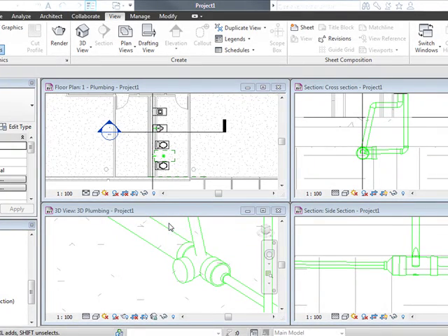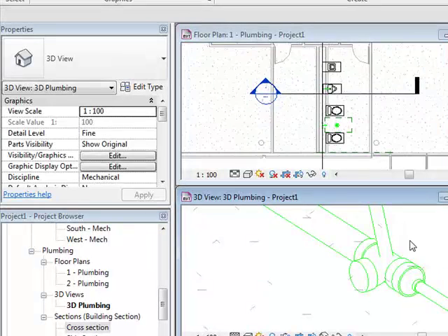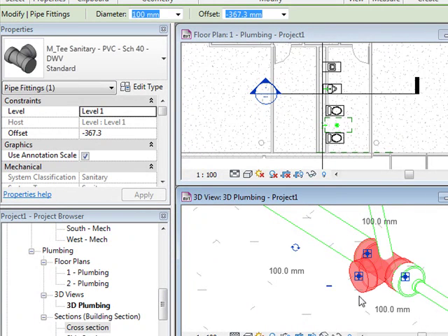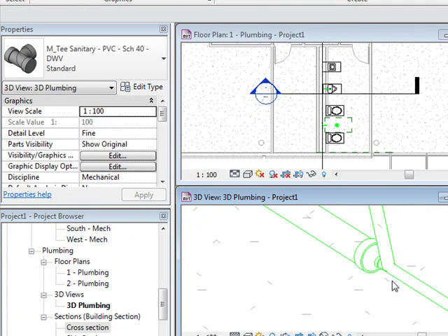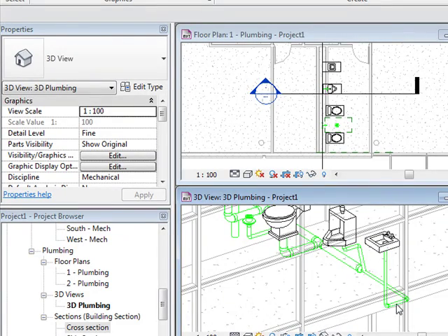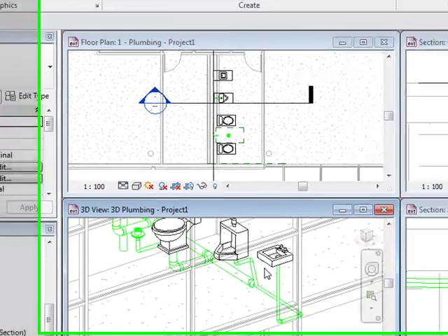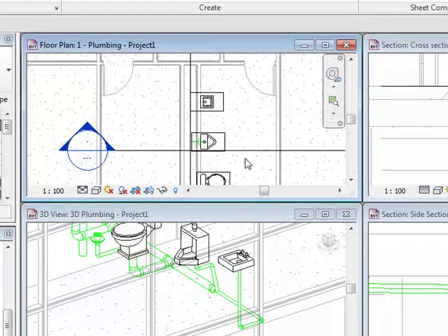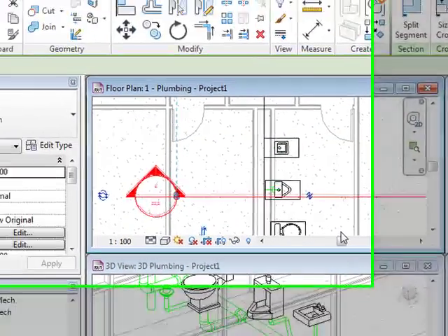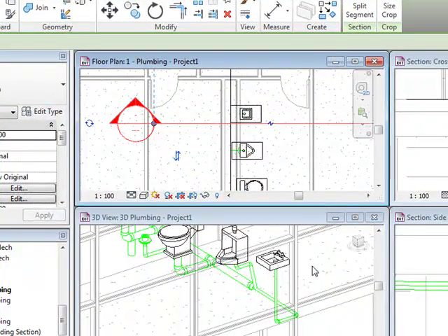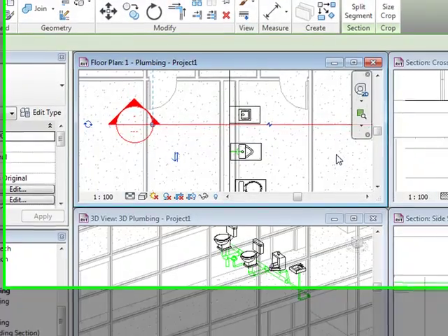Okay, for this one you need to get rid of it. So just select, go to this view and select the pipe, and you can click on the minus and it will disappear. For this one you also need to do the same thing. You just delete the pipe. You just adjust the section view first. This one doesn't matter. You can just leave it this way.